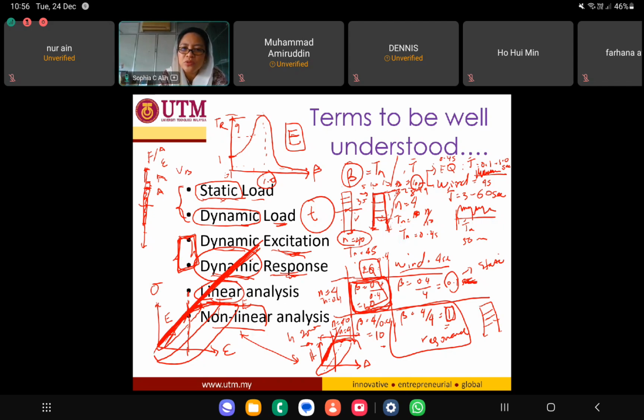But when you want to analyze what happens if yield occurs, like how much load I can impose until this beam cracks, or what load is still safe to give to my structure before this beam is damaged, linear analysis cannot give you the information you want, because linear analysis stands on the concept that it follows this line. It doesn't have any cracks. For this condition, where there is already damage here and there, it is non-linear analysis. In this class, you are not going to go for non-linear analysis.